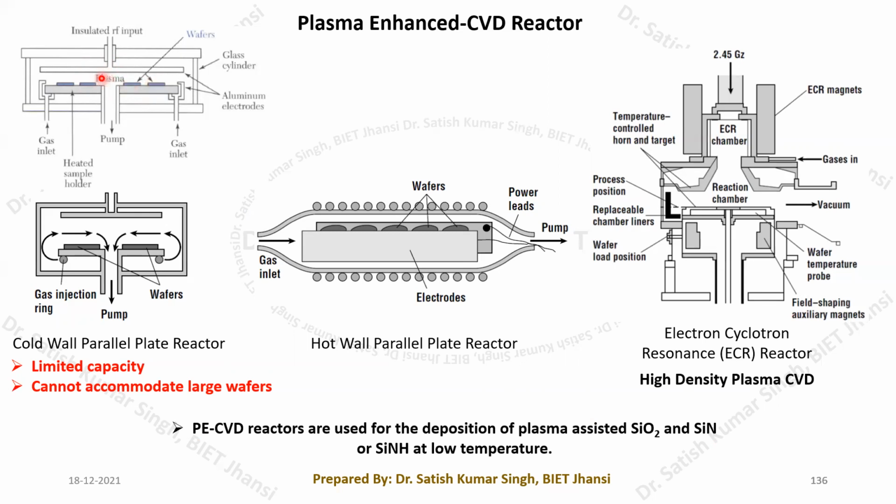Because of this glow, the reactant gases become very active. Whatever reactant gases we send inside this chamber become very active due to the glow, and then they start reacting, and the layer is deposited onto the wafer. So we have these two systems; it is the same arrangement, just drawn in a different box in a different way.